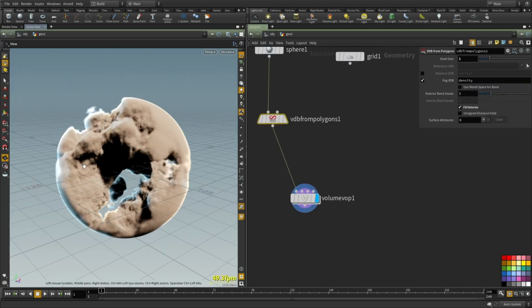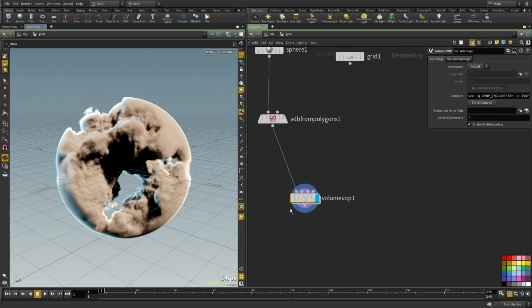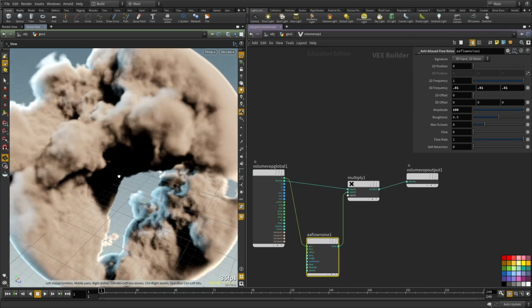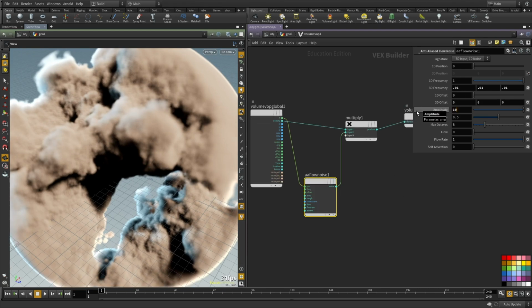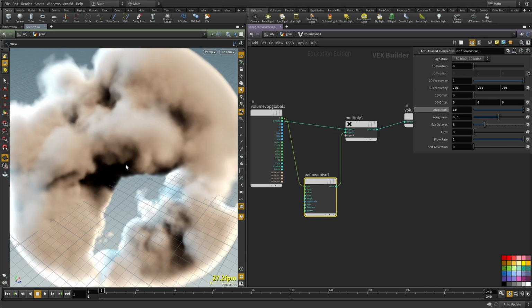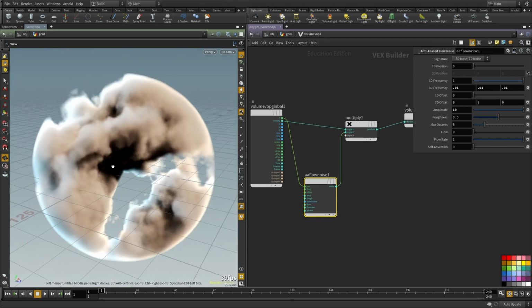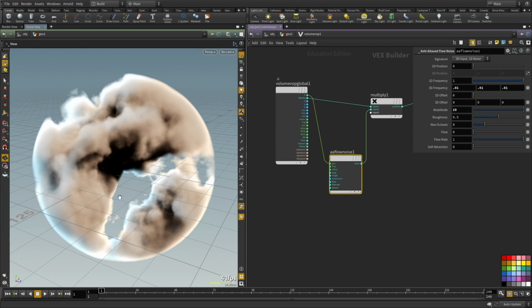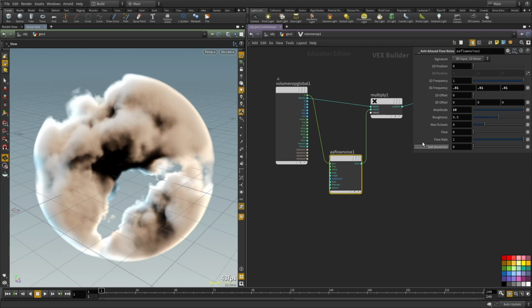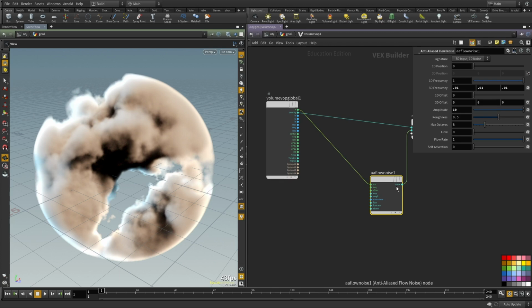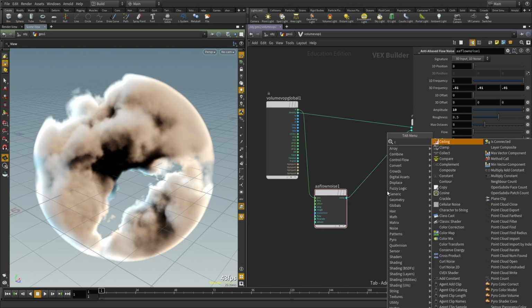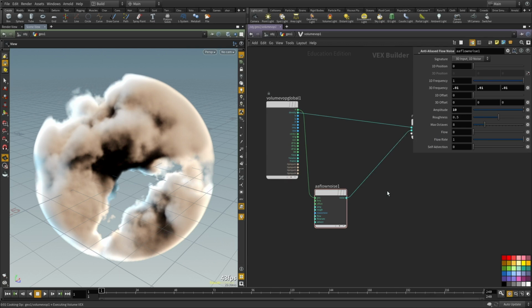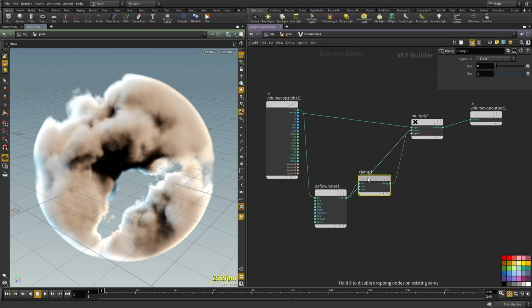Let's go back and try to play with the noise a little bit. I don't want to change it so that it removes data from here. Let's set it to 10. The reason this is getting subtracted is because this noise is returning a -1 to 1 range, so I'm going to simply clamp that and say the minimum value for this noise is going to be 0.1.